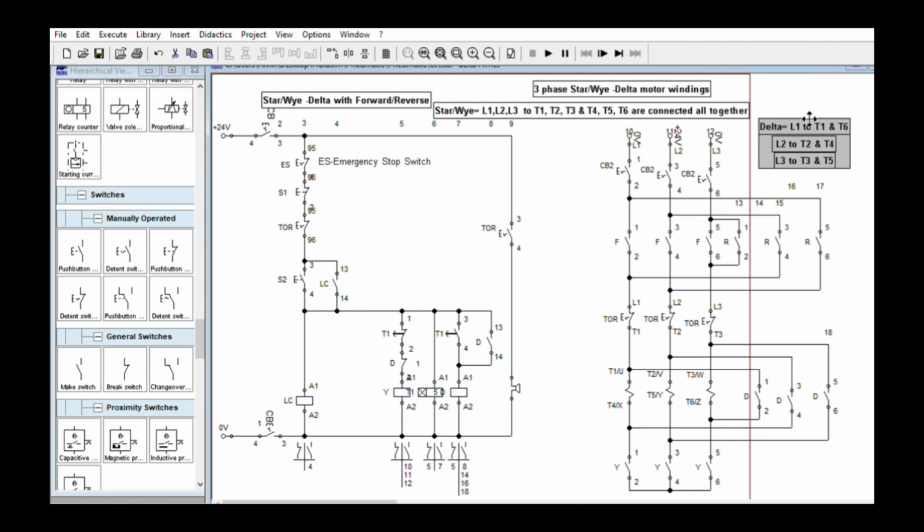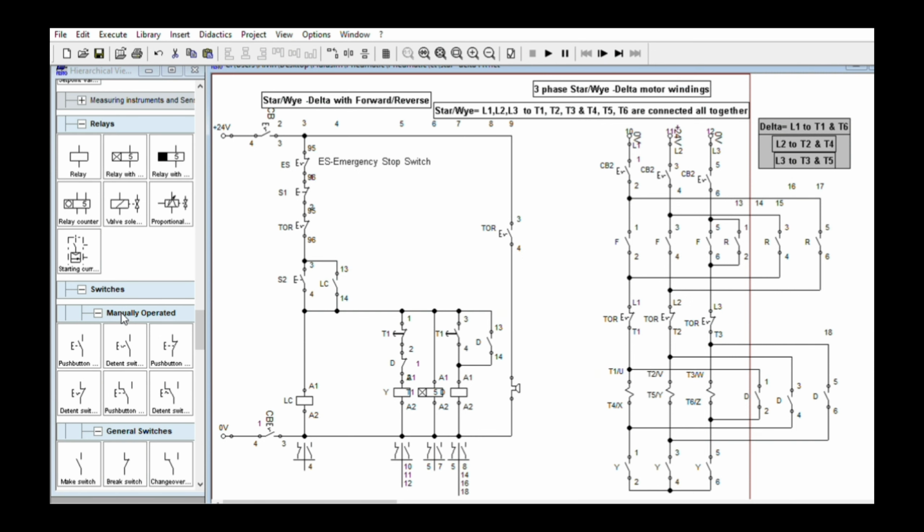Okay. We will add one contactor, one relay. This is a relay here. Don't use a relay in reality but a magnetic contactor. We are going to, of course, interlock them because we cannot turn them on together since there will be short circuit there.